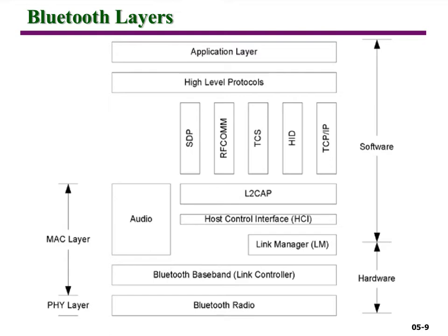So there is no adaptive burst profile like the case of the metropolitan standards. So here we have one communication scheme. As we will see later is that we do have different forward error correction schemes as part of Bluetooth, but the modulation scheme is fixed. So this is for the radio layer.